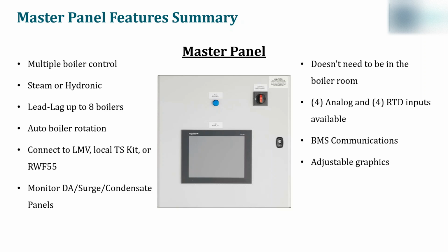And the graphics on the master panel are adjustable, so that you can make the master panel look just like the boiler room that your customer has in front of them. The master panel can also be set up with email or text messages. And this gives the ability for the master panel to send out notifications when there's an alarm, or even to send out a full alarm history or screenshots manually when you're trying to troubleshoot something.